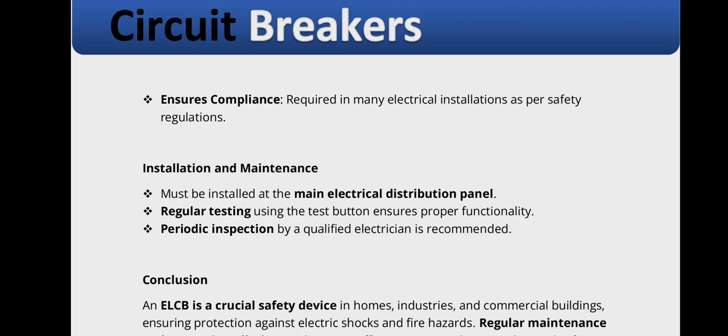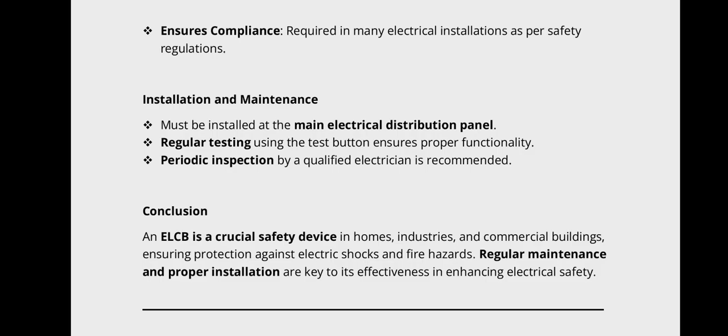Now, installation and maintenance. It must be installed at the main electrical distribution panel. Then regular testing using the test button ensures proper functionality. As we saw in our previous slide, there is one yellow button we can press for this. And periodic inspection by a qualified electrician is recommended.